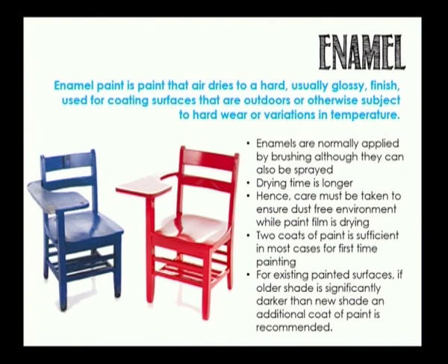Drying time: enamel comparatively takes a longer time to dry. Hence, care must be taken to ensure that there is a dust-free environment while the enamel is drying. Two coats of enamel paint are sufficient in most cases for the first time painting. For existing painted surfaces, if the existing paint is a significantly darker shade than the new enamel paint, then we need a little extra coat to mask the darker color.